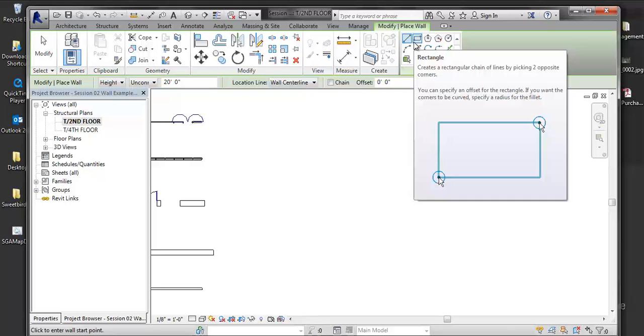And I can always tab through and change that. Really, that's just going to determine, and you'll see a little later as we get into the assembly of these walls, if I have a brick veneer on the face of one and then gypsum on the other side of those core boundaries, which side is it going to appear on?